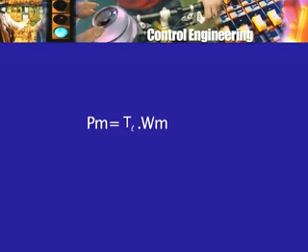Now the torque, we have to take it in Newton meters, then the product of the torque in Newton meters and the angular speed in radians per second will give us the mechanical power in watts. Now as I said, one may be used to thinking of power in horsepower units, though nowadays because we are using the international system of units, one would use the watt or the kilowatt as the unit of power. So Pm, the mechanical power, is load torque into omega m. Omega m is about 150 rad per second.